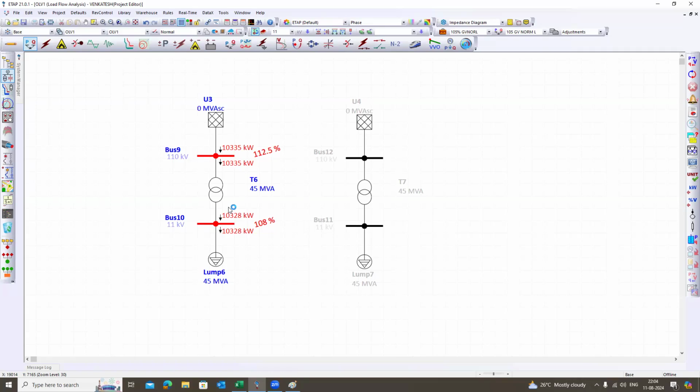Okay. But for that, we need only the upper limit and lower limit, right? Yes, obviously, because with those upper and lower limits, you will be able to maintain. See, once you decide the upper and lower limits, then in between, at any taps, your voltage of this 11 kV will be well within the permissible limits. Yes, all are within the permissible limit only. So that's what we discussed yesterday also.